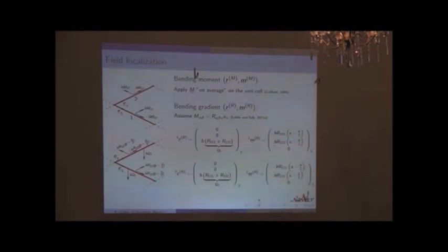This is why when you compute the shear energy of this beam lattice, and you compute the distance between the Reissner-Mindlin plate theory and the bending gradient plate theory, you can go up easily to 90%, which is purely bending gradient. And the Reissner-Mindlin is just 10% of the shear energy.